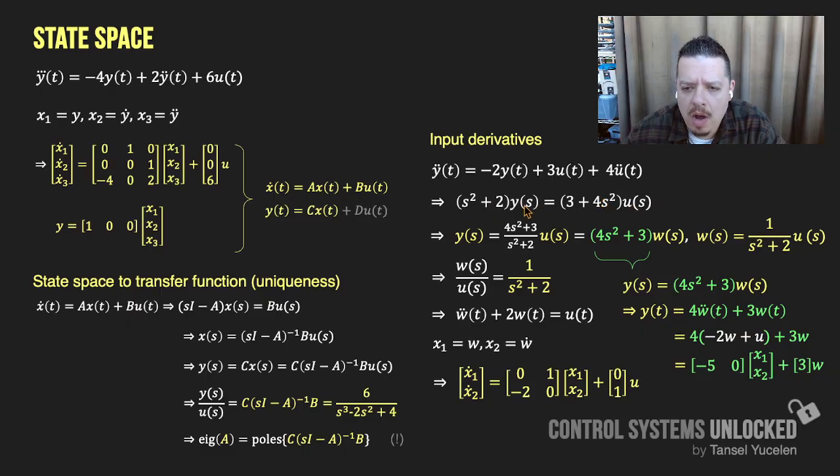And now I am trying to write it as output y equals this transfer function multiplied by u, which is coming from this line. So I am going to make its numerator green, multiplied by w, and w is 1 over s to the power of 2 multiplied by u. Essentially, this is the same transfer function, but I am breaking it into two parts.